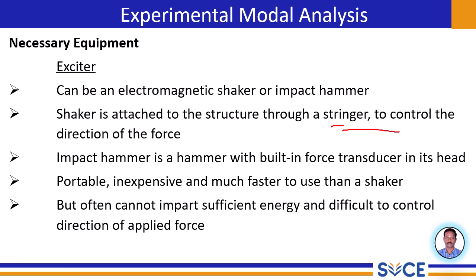Electromagnetic shakers offer a high degree of control over the frequency and amplitude of the applied force. They are particularly well suited for frequency response function testing, where we sweep through a range of frequencies or excite the structure with specific frequency content signals like sine wave or random noise. Shakers can impart significant energy into the structures, allowing us to effectively excite multiple modes. They are commonly used for more detailed modal analysis also.